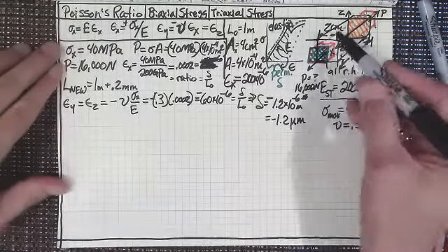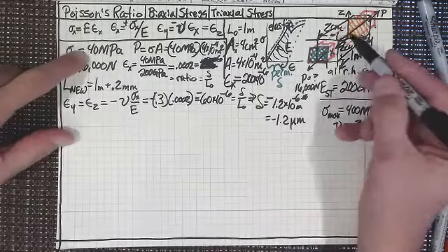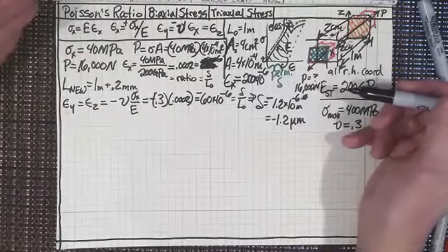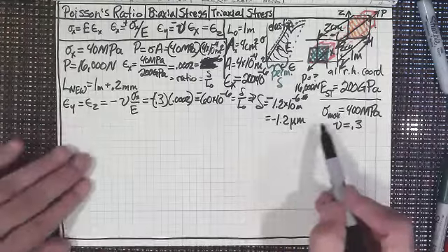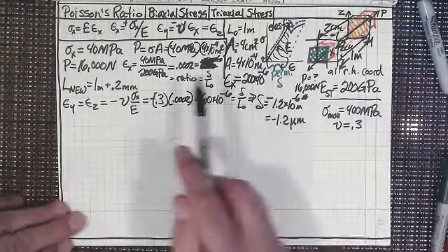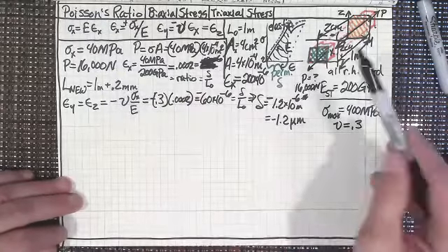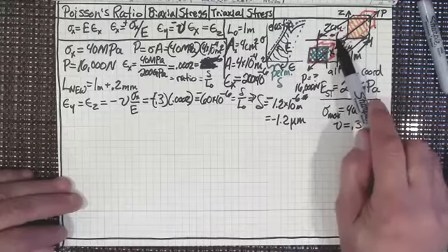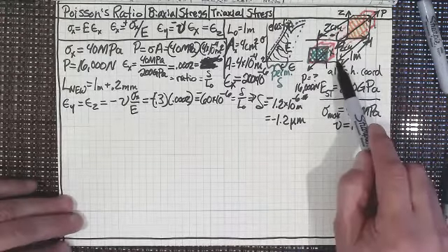So you can see that these are not going to change very much either when I put 40 megapascals on this. It's a bar of steel. We have an intuitive understanding for how much a bar of steel changes as we load it up. But you can see that's with 16,000 newtons on it. Of course, this is 2 centimeters, about an inch by an inch cross section for a steel bar.